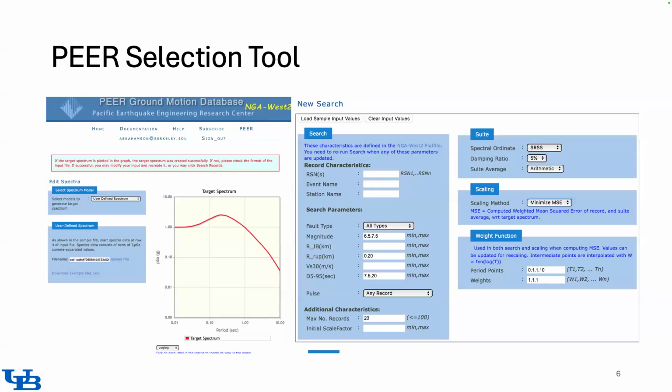If in the end what we want is a ground motion that has a consistent shape with our target spectrum, and these parameters are indirectly influencing the shape of the spectrum itself, then filtering the ground motion based on these parameters, but also trying to match the spectrum, both of them are after the same thing. So if the goal is simply to fit the target spectrum, we can have a much wider range for these, and then still filter and identify the ones that work best and use them.